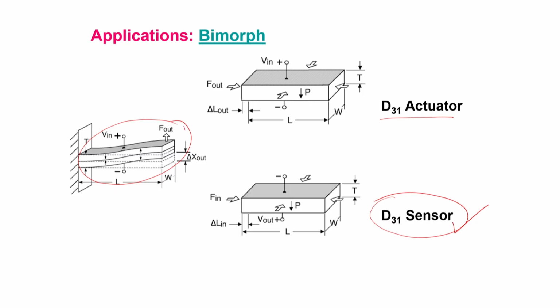So, if the piezoelectric material, as a bimorph attached with another passive material, vibrates this way or that way, that would create, in a time versus voltage plot, this vibration. This deflection that is happening here is going to create a voltage, okay, and that is the voltage that can be used for sensing.